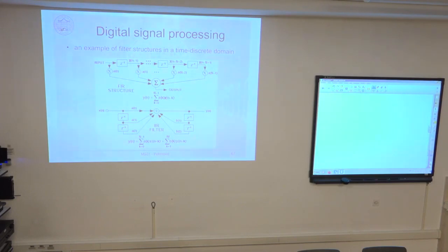You simply set the center frequency of the band that you are interested in, the bandwidth, select the type of modulation, and so on, and immediately you get from this USB output this I and Q signal, in-phase and quadrature signal, that can be used later on to demodulate this signal and to decode the message coming from the radio transmission.